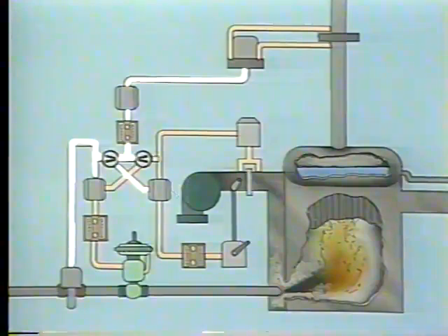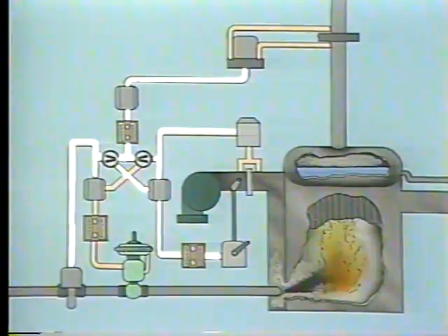The airflow controller compares the signal from the airflow transmitter to its new set point, computes the difference, and produces a corrective output signal. This signal causes the final control element to reposition the louvers in the air duct to increase airflow into the furnace.